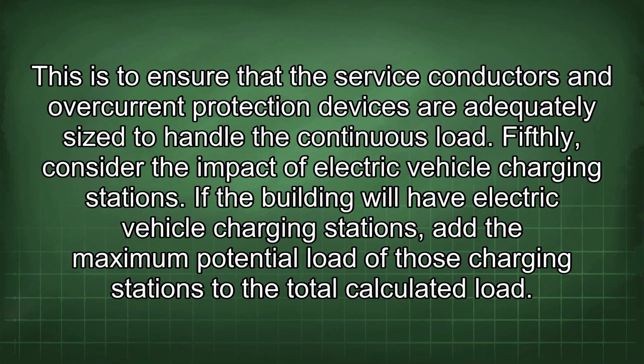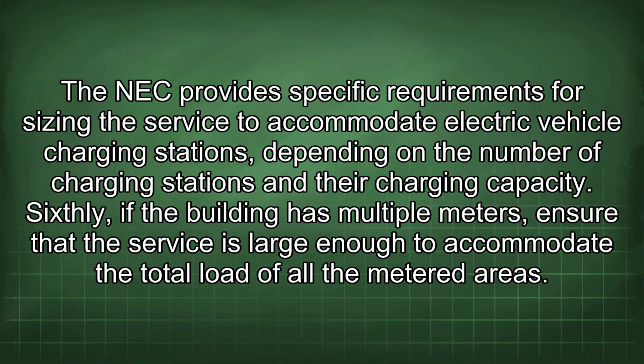Fifthly, consider the impact of electric vehicle charging stations. If the building will have electric vehicle charging stations, add the maximum potential load of those charging stations to the total calculated load. The NEC provides specific requirements for sizing the service to accommodate electric vehicle charging stations depending on the number of charging stations and their charging capacity.